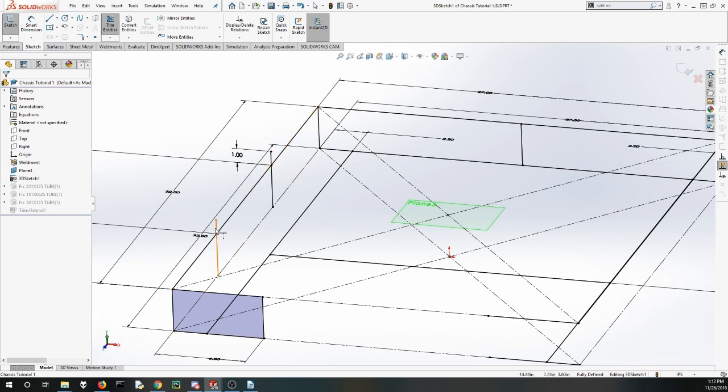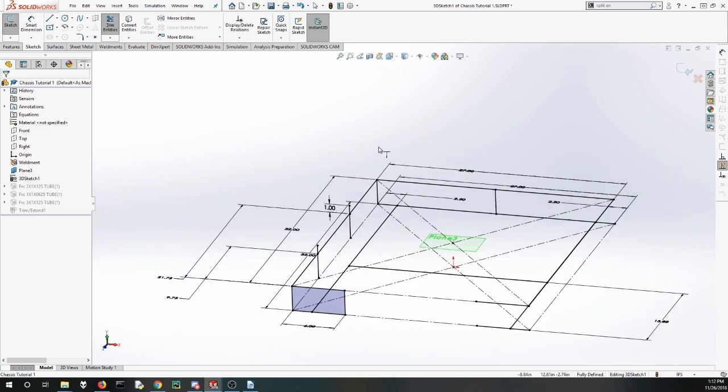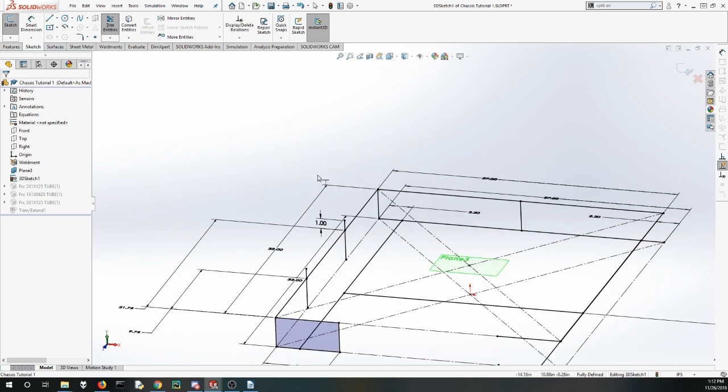I created the construction geometry first because if I just click Extend on some line with nothing past the endpoint to stop it, it doesn't have a defined endpoint, so the line would be infinitely long and SOLIDWORKS can't create it.